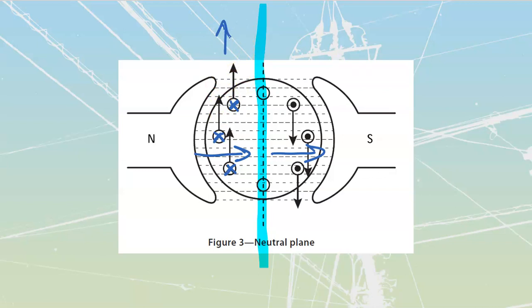We'll do the same now on the opposite side of the line. Once again, right-hand rule. First finger in the direction of the fields, center finger in the direction of current. So now your center finger should be pointing up towards you, thumb in the direction of thrust, and you're going to see that for all of these, the thrust is going to be downward. So on this side over here, we have that central axis. On this side, it's going to be pushing up.